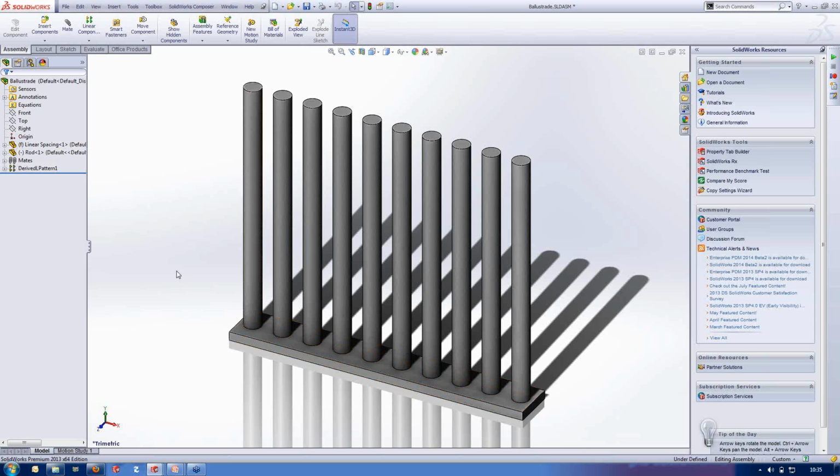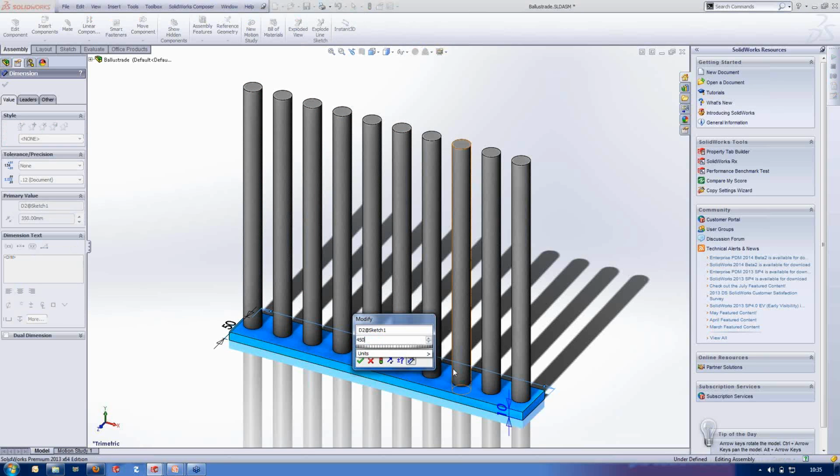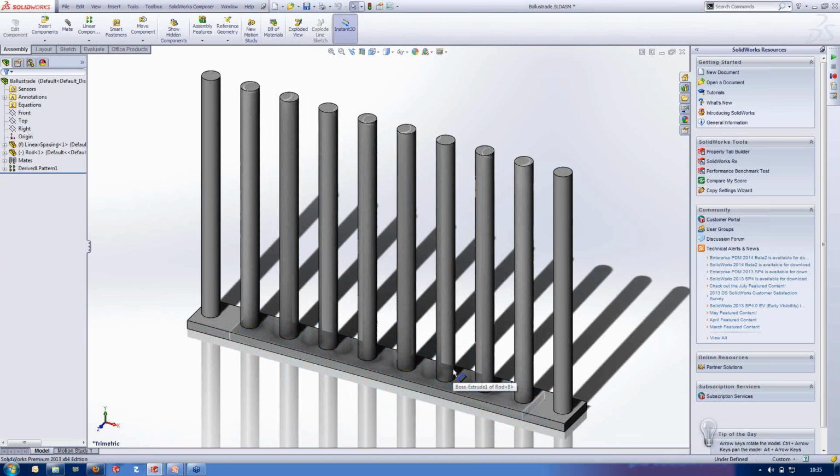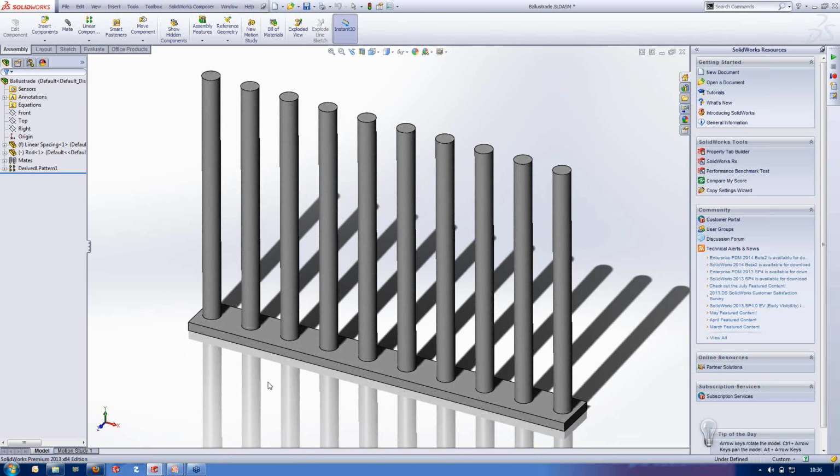Now this can be used along with the assembly feature, the feature-driven component pattern, to make balustrades really easy to calculate. So this is the same part in the bottom, controlling the spacing, and I've just stuck a very simple rod in it. If I change this dimension up, the assembly will cope with all of those changes. So it's very quick to keep all my changes, all my assembly building working the same way, and control all the spacing very quickly. So that's some really useful examples on using the if statement and the equations to drive things.